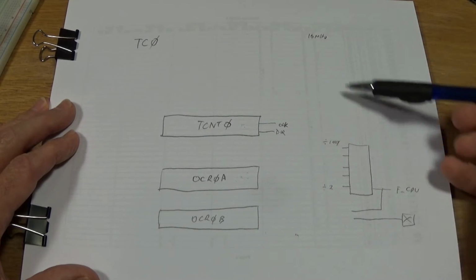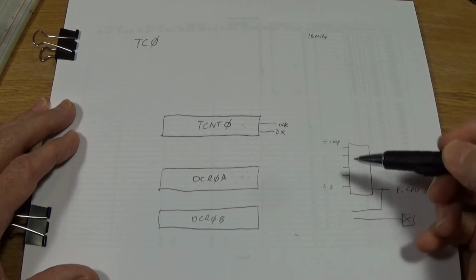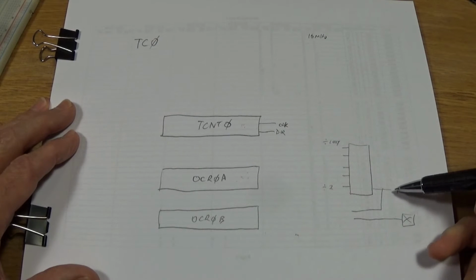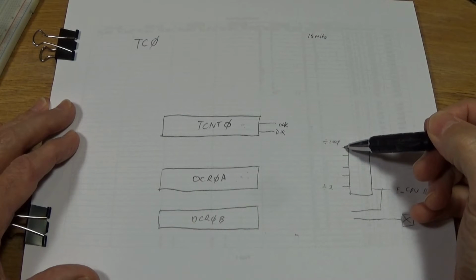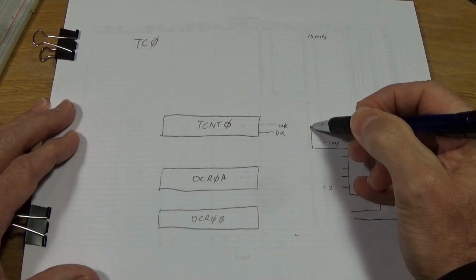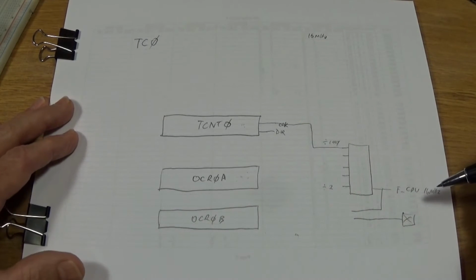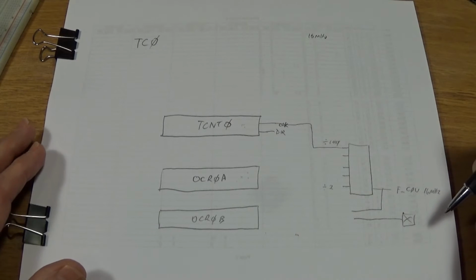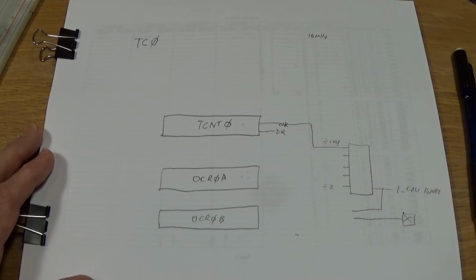If you take this 16 megahertz from here, and you put it into the Prescaler and you pick one of these taps, you can slow this timer down to a reasonable value. And what I've done when I set it up is I'll choose the 1024 tap here, and so it's going to be going into the clock register here, or the clock line here. And I'll have to sit down and do the math here. In fact, what I'll do is I'll stop for a moment and then I'll do that.